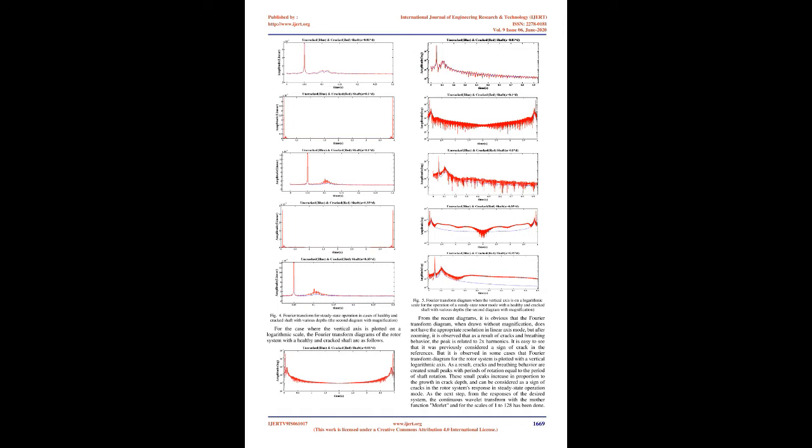It is a bit more difficult to analyze such cracks because the change in the stiffness of breathing cracks itself depends on another factor. That is the weight of the shaft, because in heavy shafts, static deformation is greater than the amplitude of vibrations, and linear and time-variable behavior can be considered for the breathing of the crack. However, in light or weightless shafts, compared to other components connected to the shaft, such as discs and blades, the opening and closing situation of the crack is a function of the vibration amplitude, and nonlinear behavior will be created.